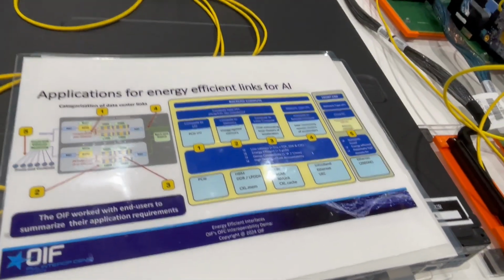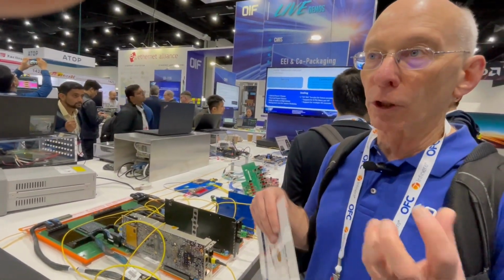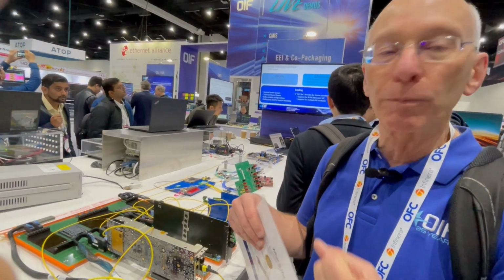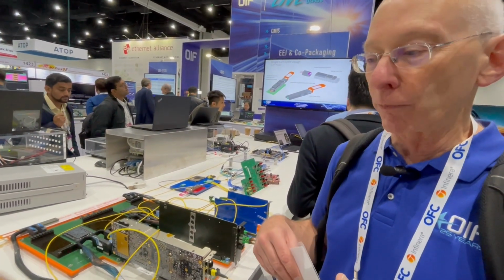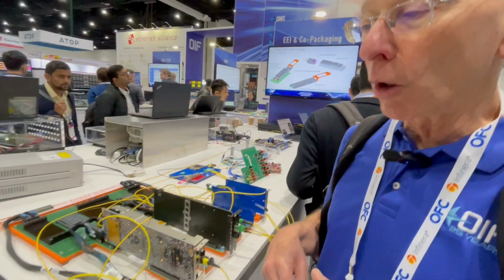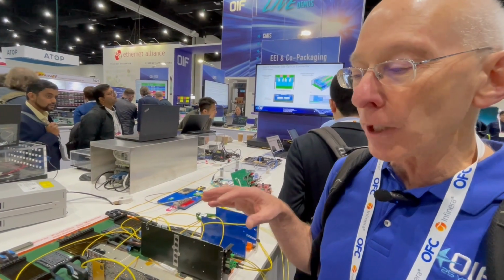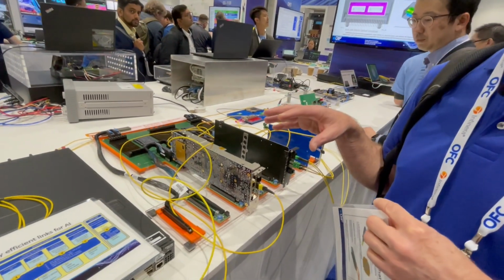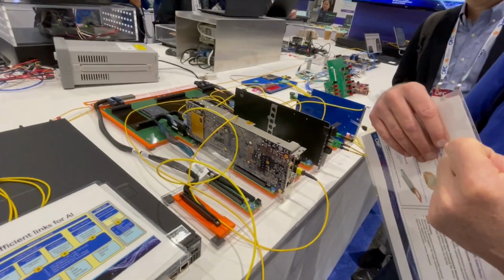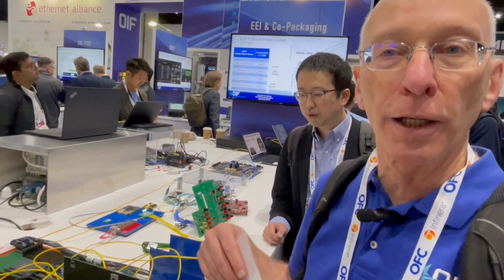And the goal here, when we do AI computation, is these problems are broken up into tiles, and there's lots and lots of parameters, and all that data has to be moved between the various GPUs because you don't finish a calculation until all of it's done for a particular section. So the time of flight, the latency and the SerDes, and all those factors affect how fast you can get things done. So we're looking at the interfaces between the GPUs and how we can make them more efficient. And when you make them close together to get the latency down, you also have to worry about power, because power consumption turns into a thermal problem. Yes. So by making these more energy efficient, we do that.